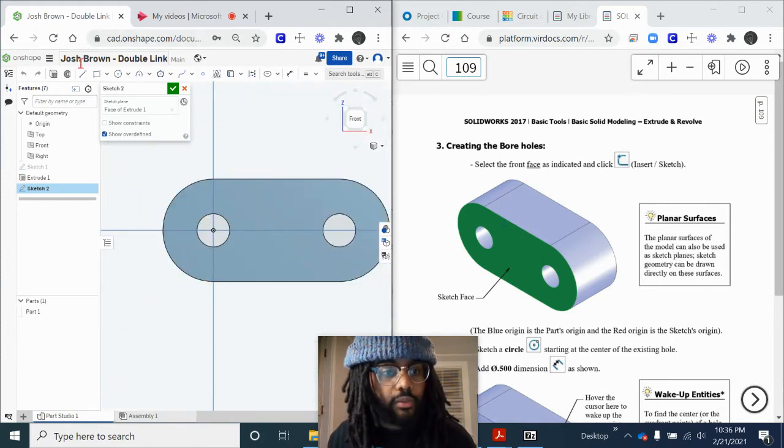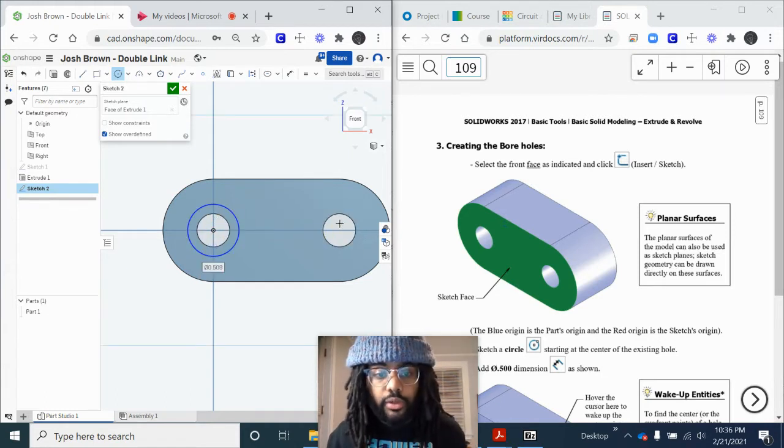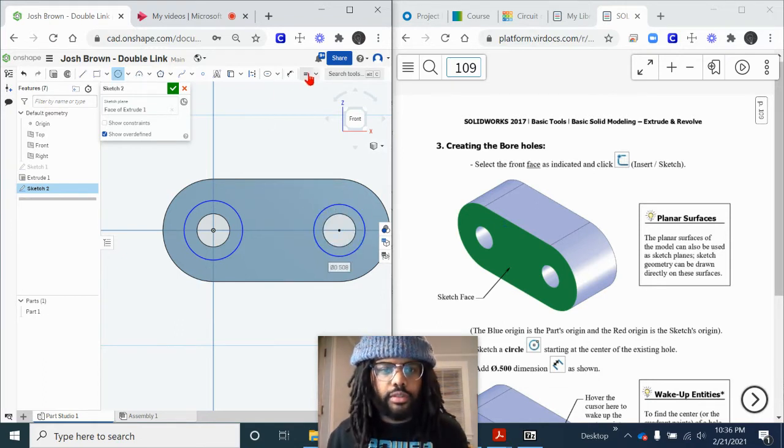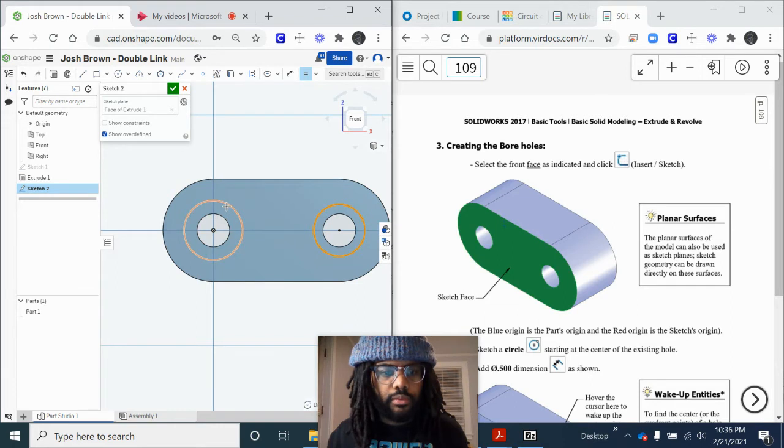Now at this point, we're actually going to draw 2 new circles. And remember, if you hover over here, you'll see right where you can click and drag where that circle is. I'll do that one more time for you guys. If I click circle, I'm going to do it from the origin, of course, no problem. But if there's no circle here, I can wait till this yellow dot comes right there. You see it? You can see it right there, yellow dot. I want to do the same thing. I want to make both of these equal.